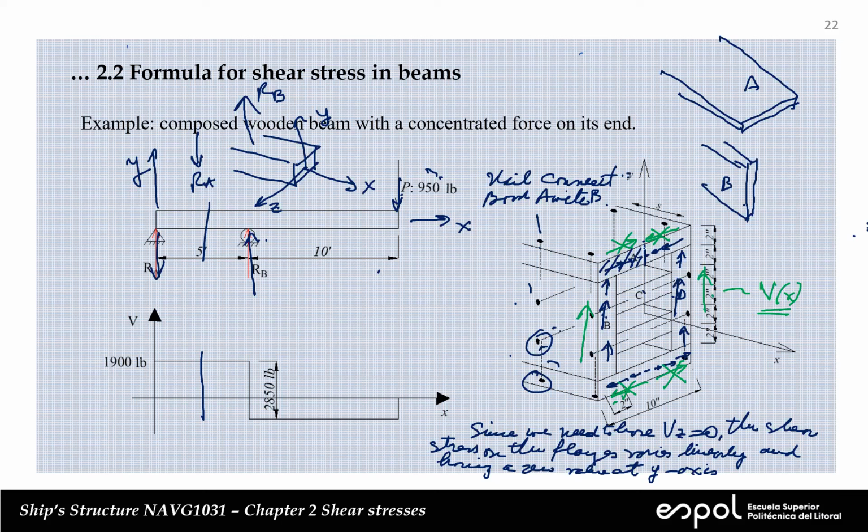No, that's not the reason. Up to here, that's correct. Because we have other nails on the other side. No, that's not it. Remember, because it's 0 at this point. That's the answer, right? Because if we cut here, we're going to have a shear stress in this cut with a certain value. And if we make a cut here and we do not know the value on this cut, we're going to have two unknowns, but we have only one equation.